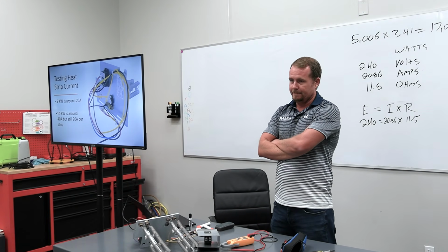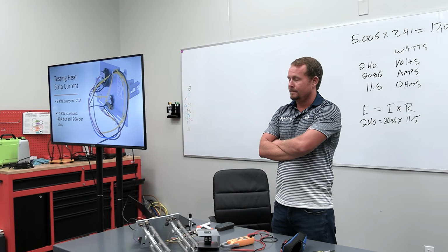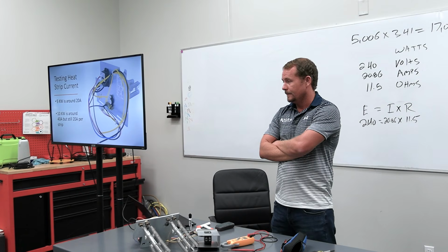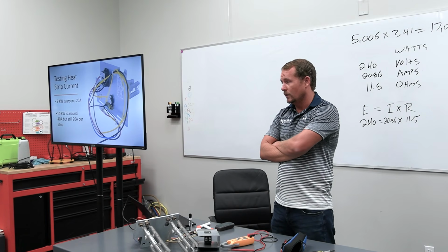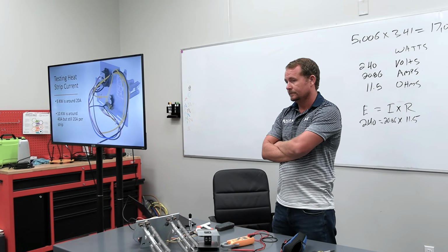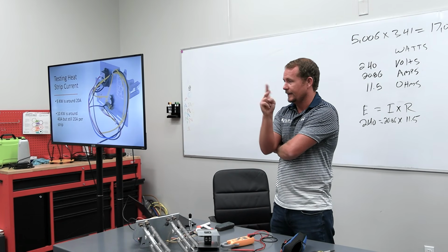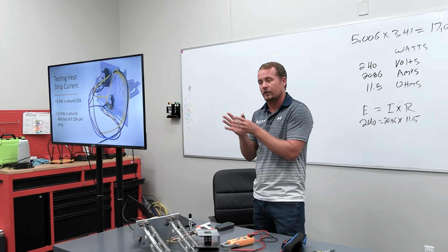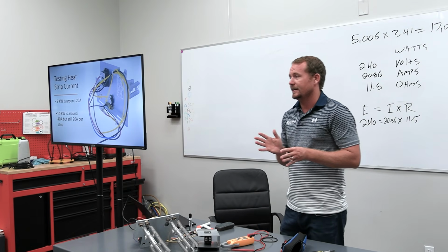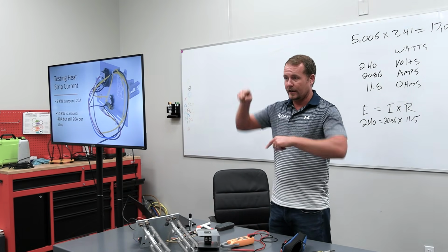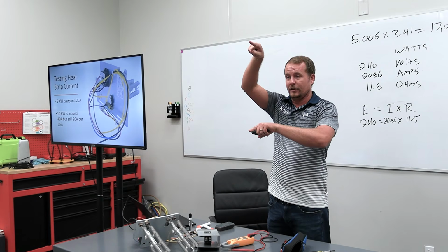But it's 3-phase, right? You're going to get 120 on these? No, you get 120 still, because from leg to neutral, it's the same. It's from leg to leg. The two legs are no longer 180 degrees out of phase like they once were. So 180 degrees out of phase means that they're like this.